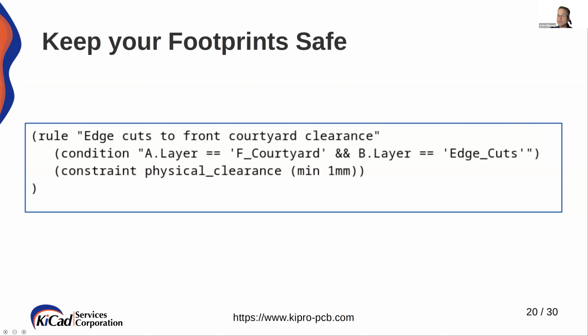You can do it using areas that we saw earlier. You can draw your areas around where the edge cuts is and specify them that way. And you can also limit them based on the properties of the edge cuts lines themselves, of the edge cut elements themselves.